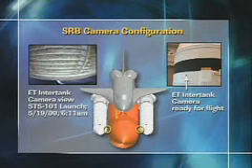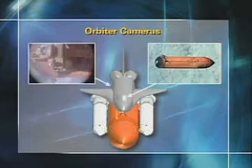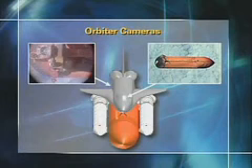Lastly, on the orbiter cameras, as I mentioned, we've upgraded 2 of those cameras. It's the same set of cameras that we've used in the past for ET separation, except that instead of being film cameras, we've upgraded those to digital cameras. John has already talked to you about that crew handheld. Since we've flown those in the past, it was just a case of telling the crew to use that to do the imagery of the tank. But the umbilical well camera we've updated to digital, so we get really good pictures of the ET surface and the foam that we can downlink to the ground during the mission itself instead of waiting to landing and pulling the data out of the orbiter.